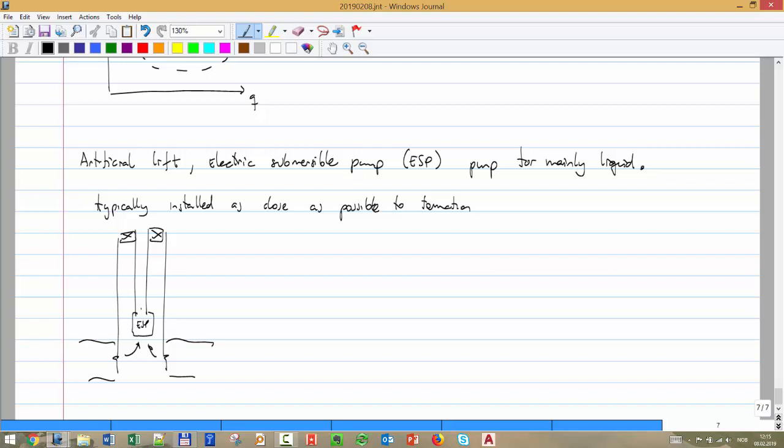So when you make your equilibrium calculations, you make it at the bottom hole, typically. PWF, so you get one curve, which will be simply the formation or the IPR, and maybe some height difference, not much. And then you have your tubing, we call this equation TPR, the tubing, and that will be the pressure at the discharge.